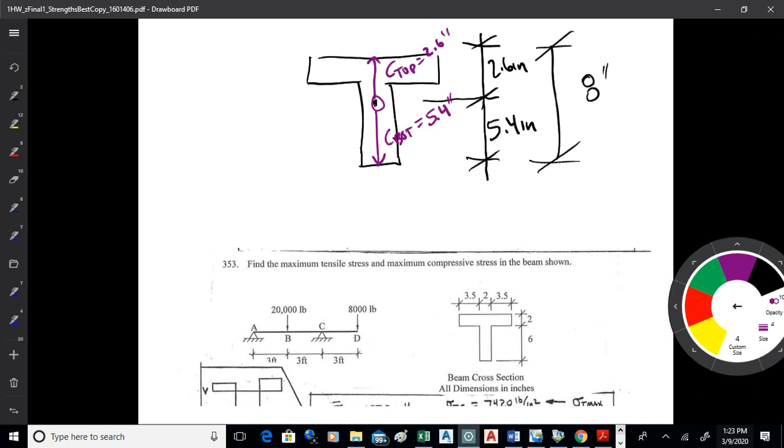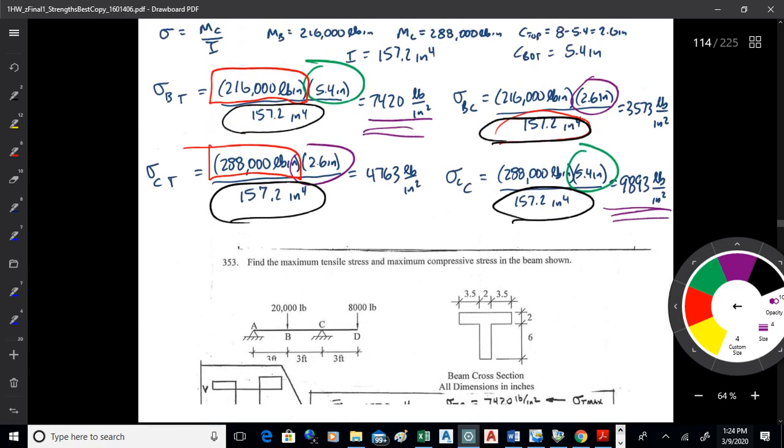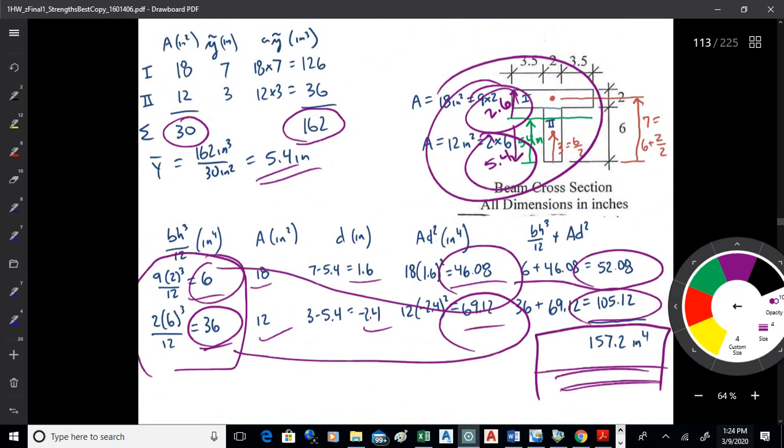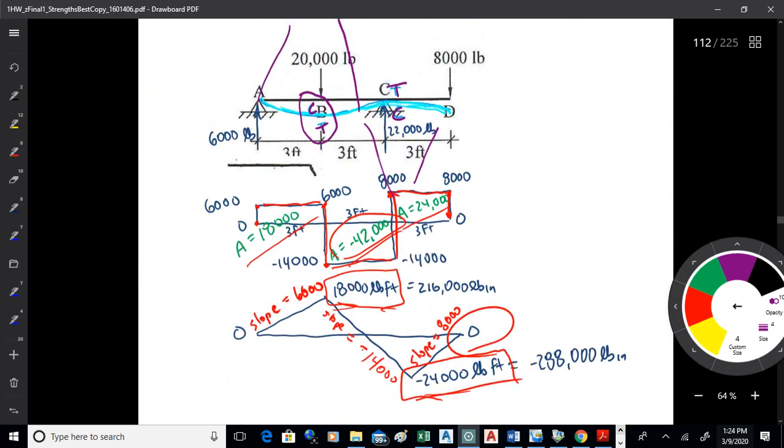How do you know what C you're supposed to use in the equations? Okay, the way you know which C to use depends on the moment diagram. And what's happening with the moment diagram on this is it flips, basically, because you've got an overhanging beam. So the moment diagram is right there, and let's clean it up a little bit.